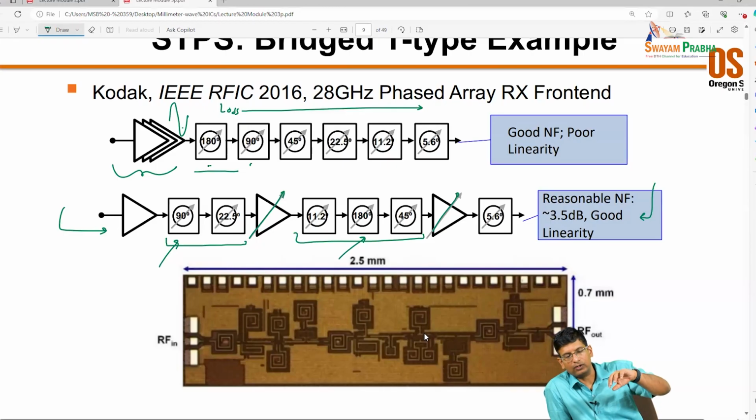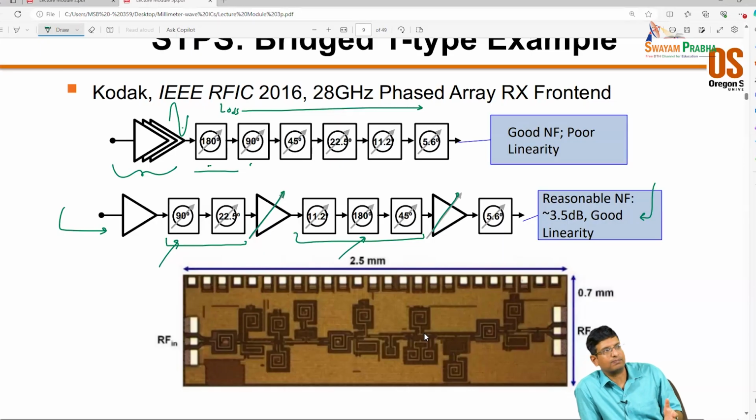This is again part of the reason to design things matched, right? Because if I design things matched, I can experiment with these orders, right? If everything has the same characteristic impedance, doesn't have to be 50, it can be 60, whatever. But then the other thing is that I like to test breakouts of these. So if I'm trying to test breakouts, better to design for 50 so that my breakout test is simplified, right? So then I just end up with everything on my chip looking like 50 ohm matched input and output networks.